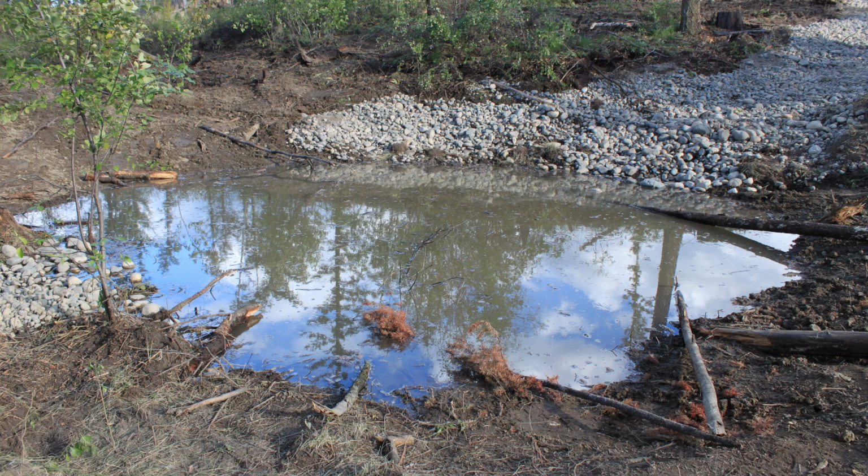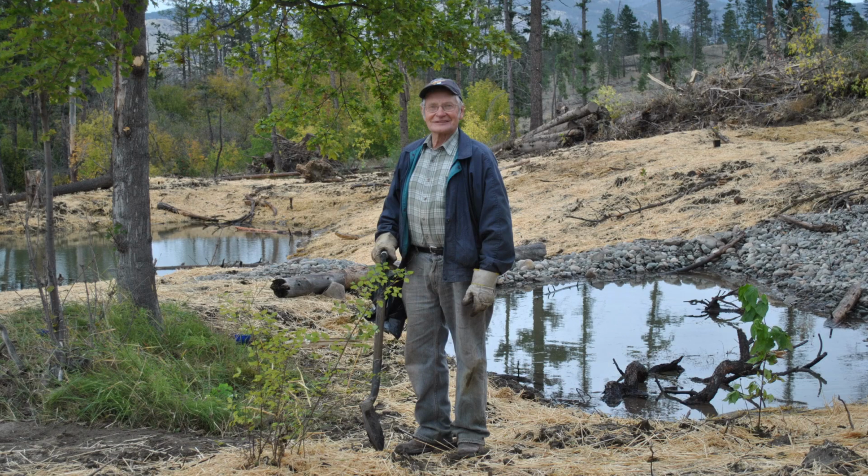Very few people like the appearance of rock that's used to control erosion on a wetland project. To help hide the rock, I recommend spreading soil between the rocks and spreading a thin layer of soil over the top of the rocks so that plants will grow. The dedicated volunteers sowed seeds from native plants, they planted native plants, and they added large woody debris and then mulched the spillways and the soil surrounding the wetlands with straw to control erosion.